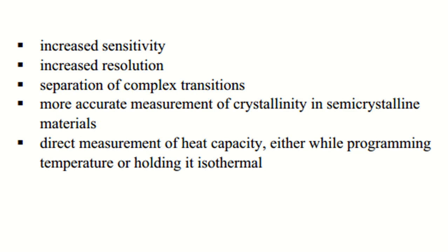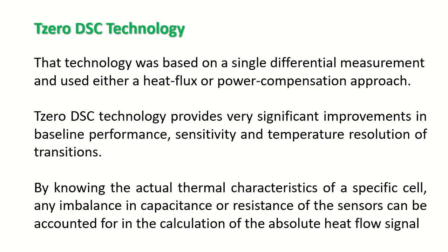Here are the increased sensitivity, increased resolution, separation of complex transitions, more accurate measurement of crystallinity in semi-crystalline material, and direct measurement of heat capacity either while programming or holding isothermal, which are advantages over conventional DSC. Some of these benefits we have discussed, and we will discuss them for pharmaceutical materials in later lectures.